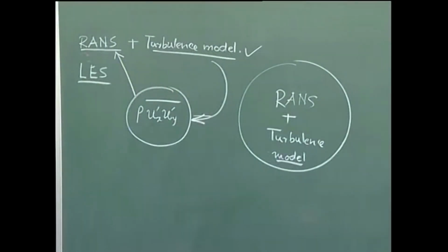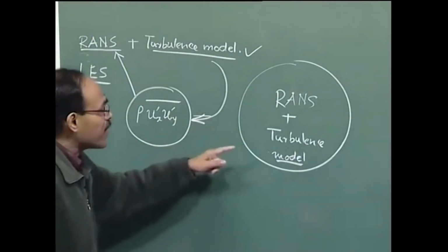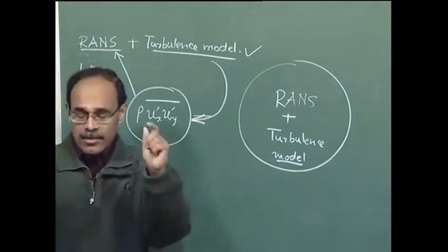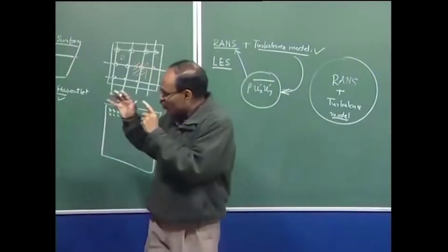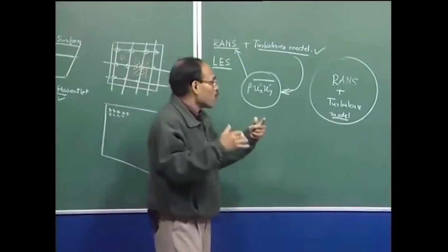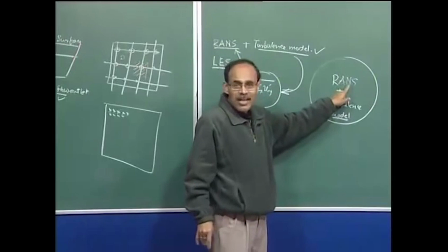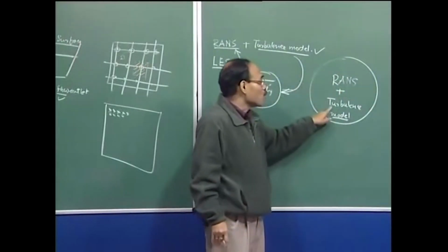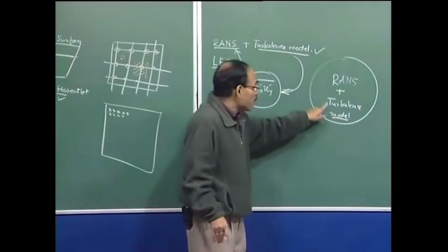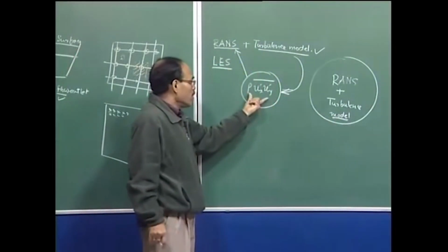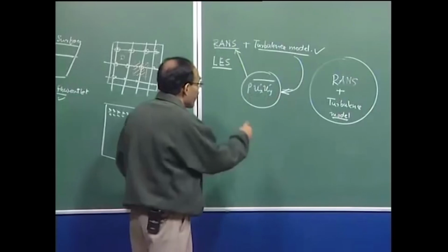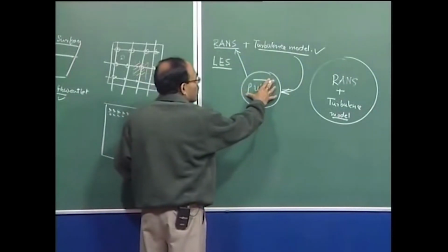As far as steel making is concerned, if you want to calculate the flow of melt in steel making reactors, the flow model, or the theoretical framework for melt flow calculation, will comprise the RANS equation, and along with this we will require a turbulence model. The purpose of that turbulence model is to provide an estimation of, or information on, the distribution of the turbulent shear stresses.